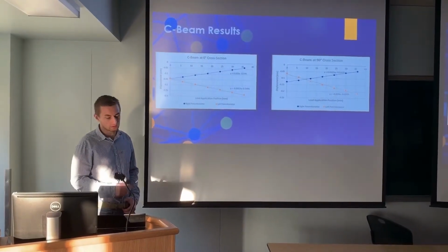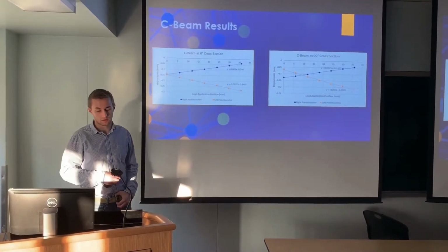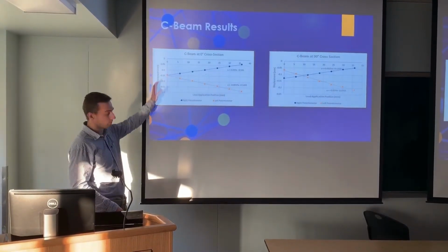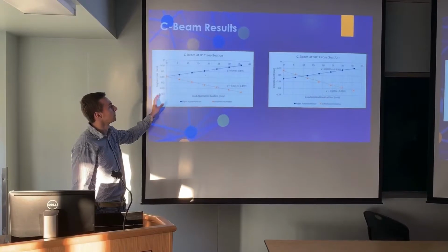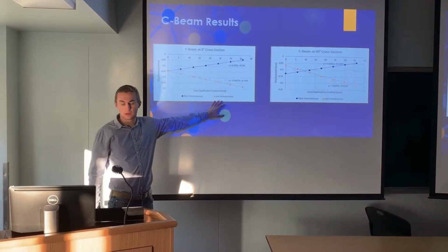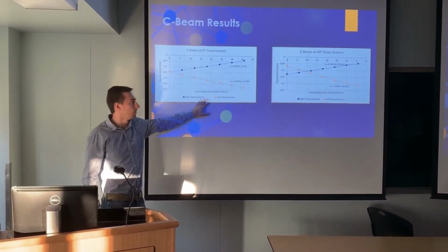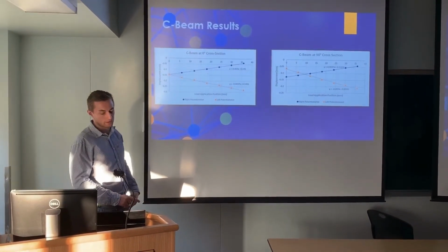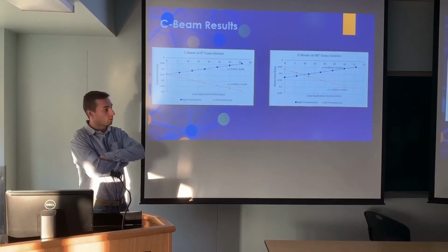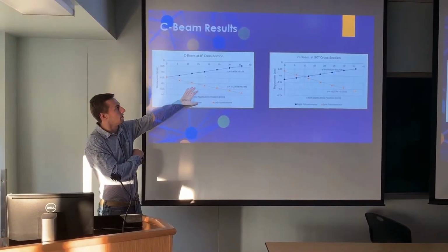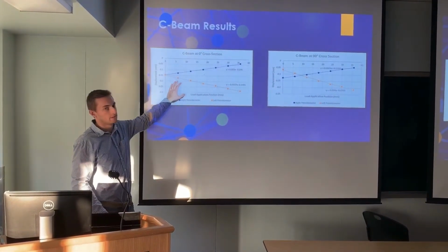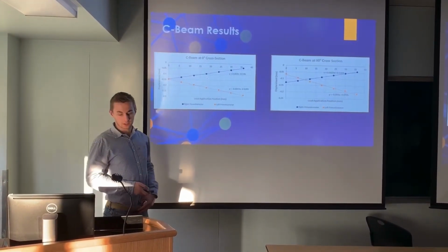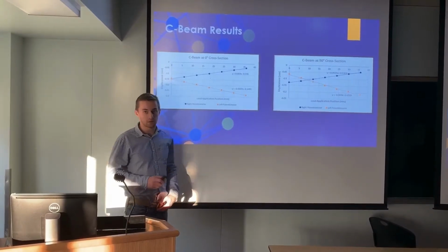In these figures, the twist of the beam is plotted as a function of load location on the cross-section. The y-axis values are the displacement from our linear potentiometers, and the x-axis values are the location at which the applied load was. As you can see, the potentiometer on the left side of the cross-section is shown in orange, and the potentiometer on the right side of the cross-section is in blue. The resulting intersection of the graphs gives the coordinate position of the shear center.